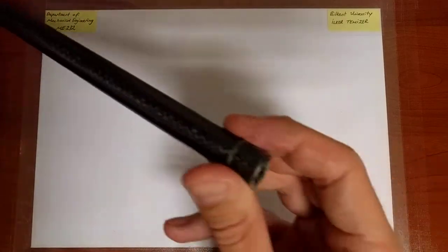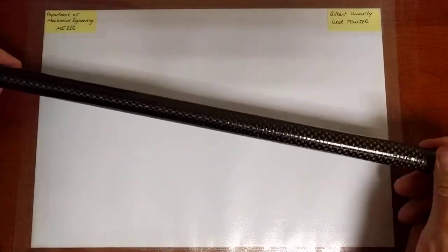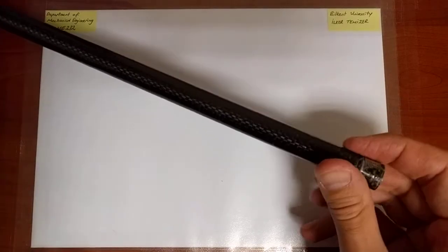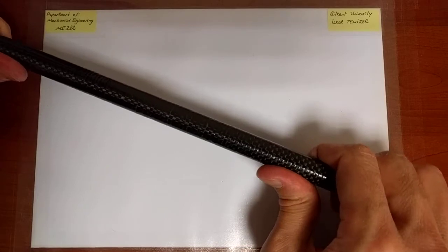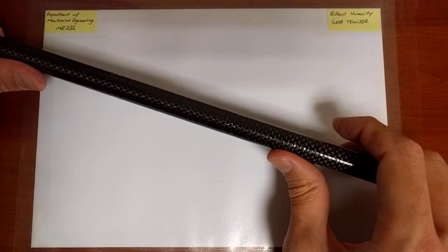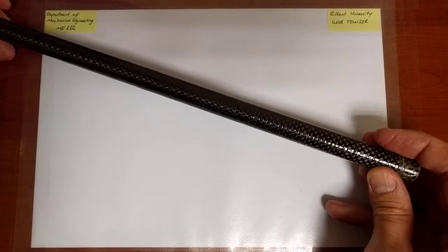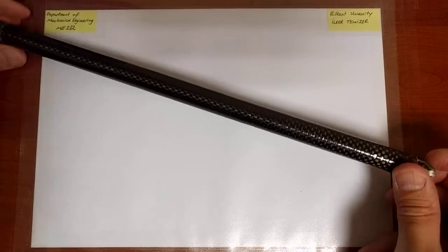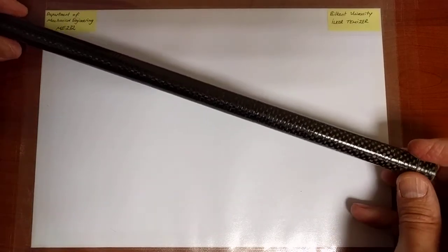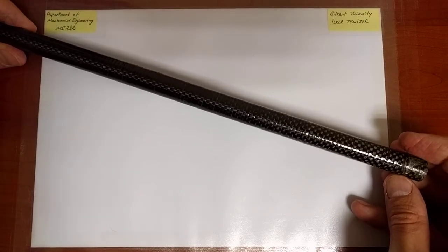Here's a carbon fiber tube, right? It's hollow in the center. And now, why would you like to build something out of composite? Because the idea is if you would like to achieve the same strength and modulus with, say, steel, it would be heavier. So if you want to do something that is lightweight, carbon fiber composite, for instance, could be a good choice. And this is at least a structure that's slightly more complicated with respect to geometry than a plate.